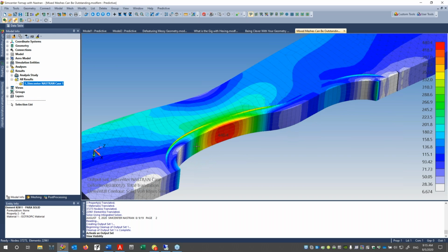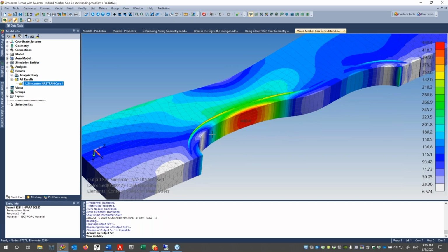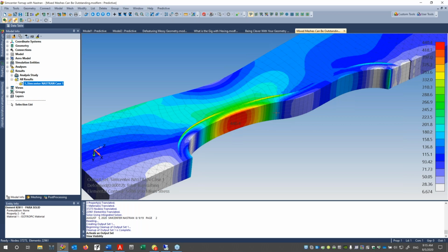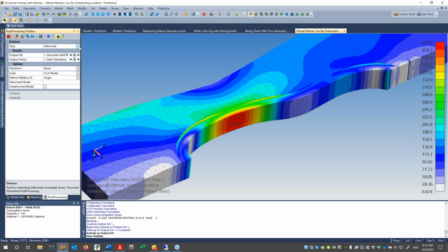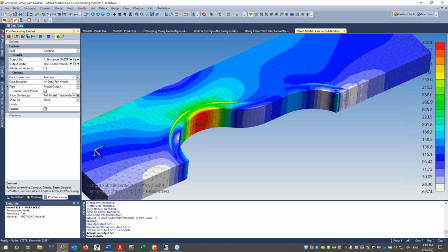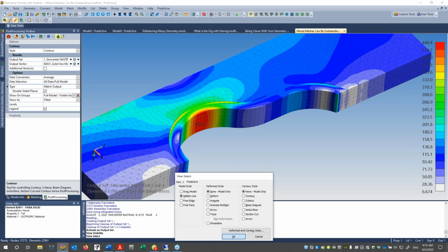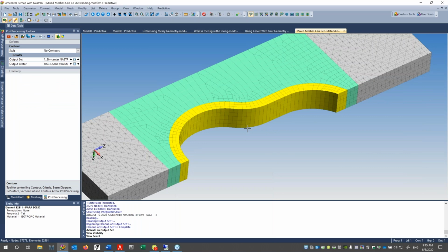If you do your research on the pyramid element, it's another isoparametric, but it has a very clean shape function match between the TET and the 8 node. And there's research papers that show it's all good. So what do we do here? Let's go back in. You guys notice that I didn't automatically hit F5, the view options. It's hard to break habits. I'm trying to get to using more of the toolbox.